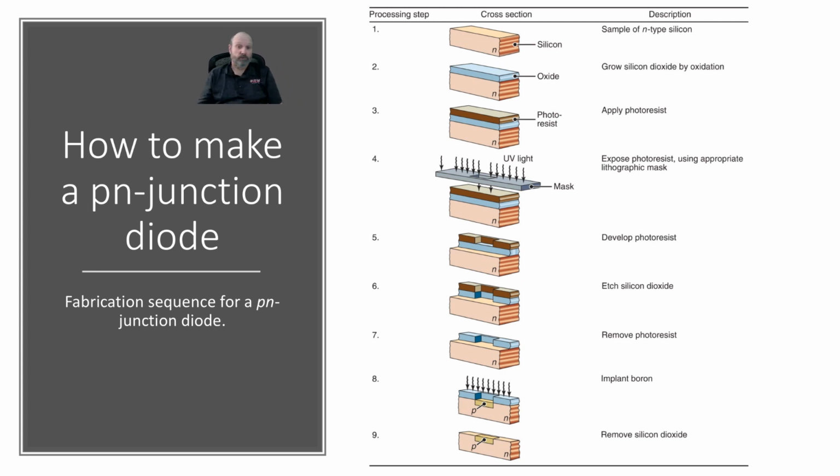So, when it gets to a certain thickness, it just stops growing. Now, we can increase the thickness of the oxide if we put it in temperature. So if you ramp up the temperature from room temperature, which is about 20 degrees Celsius, up to 1,000 degrees Celsius and put it in an oxygen environment, then the oxygen is now moving at a much faster rate, right? Because higher temperature means the molecules in the air are moving much, much faster.